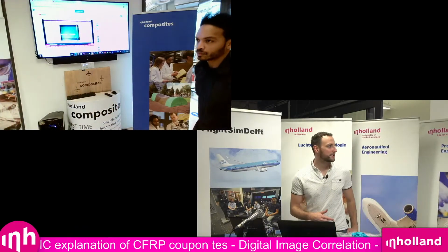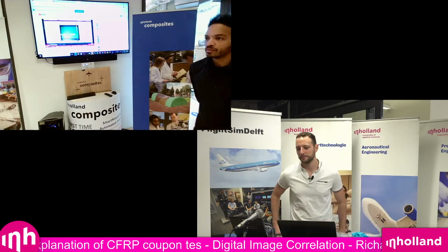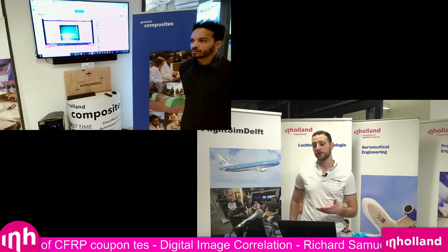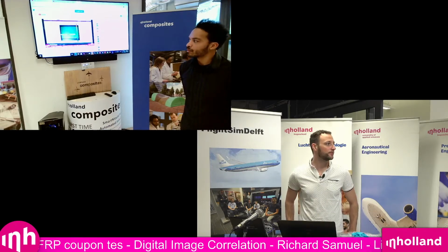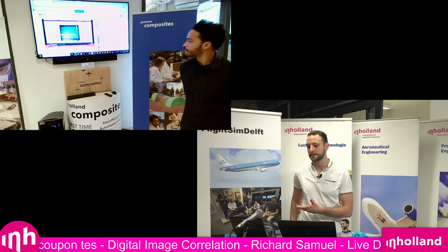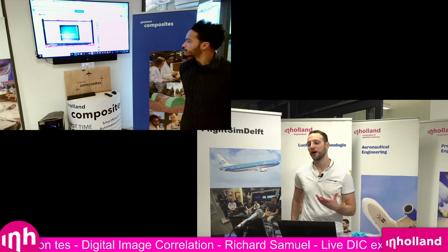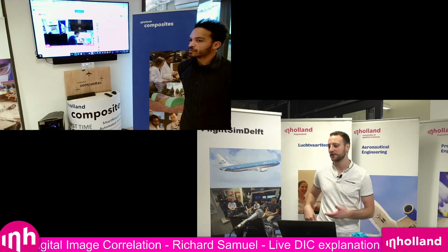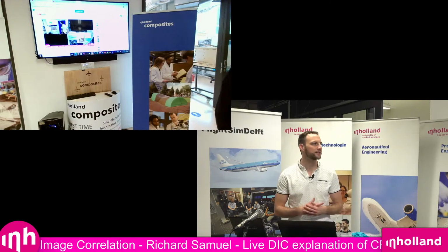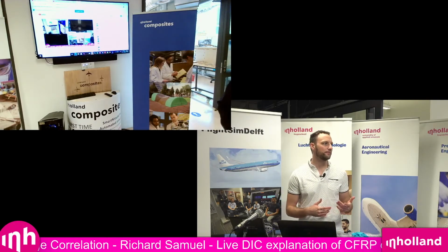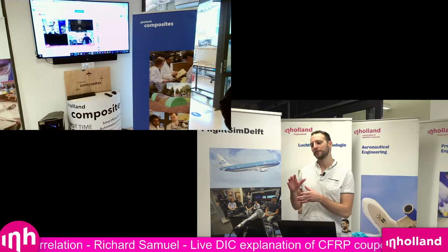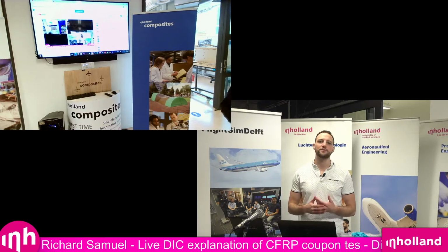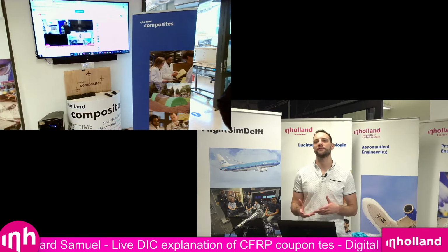A lot of the testing that I did with this setup is purely 2D. There is a lot of research that is done on 3D test setups. I can't vouch for how accurate it is, but it is an upcoming technology. It's a very young technology that's got active testing. The only thing is, every DIC test setup is specific to what you're testing for.